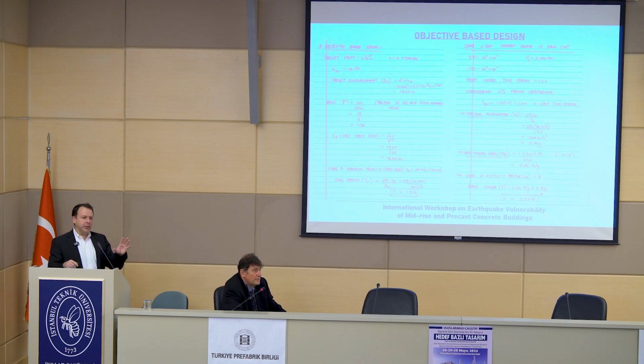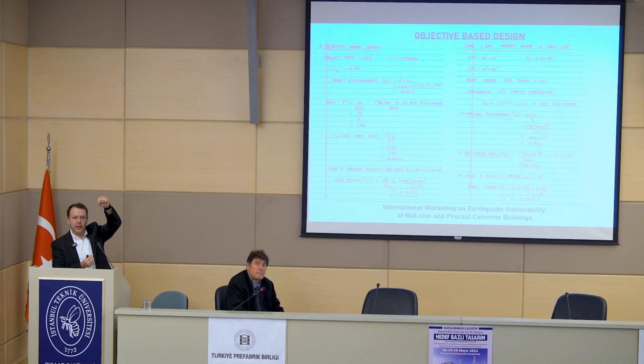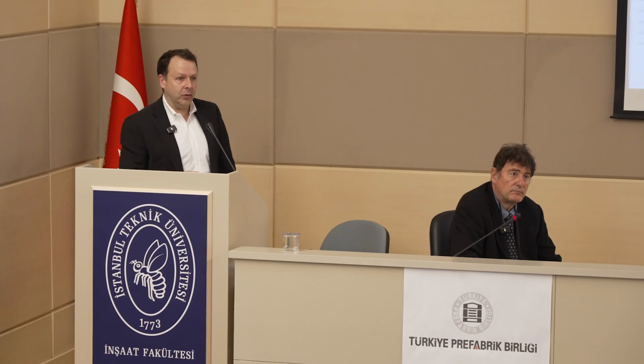These are very simple equations that go back to fundamental structural analysis, and it's a parametric equation to define, if you imagine a beam that's hinged at halfway, columns hinged at halfway their story height, you apply a deformation, and with that you can size all your members based on the target period that you have as well.